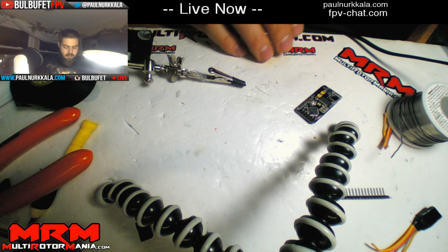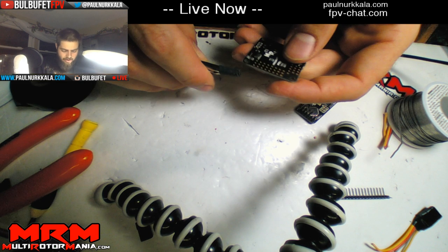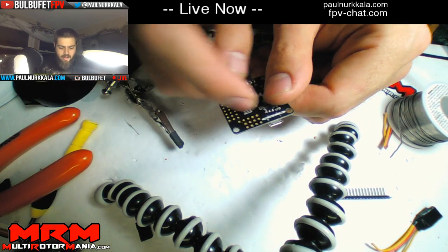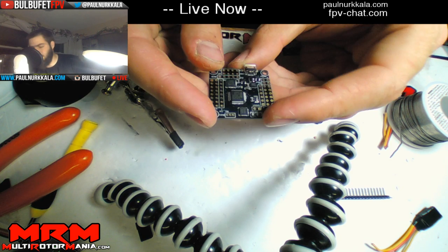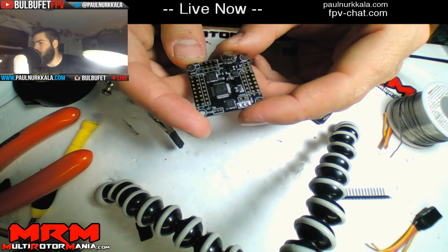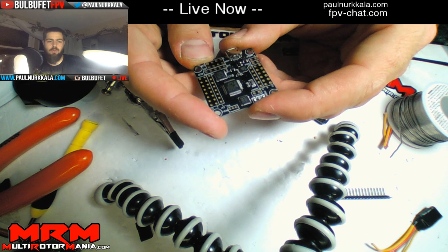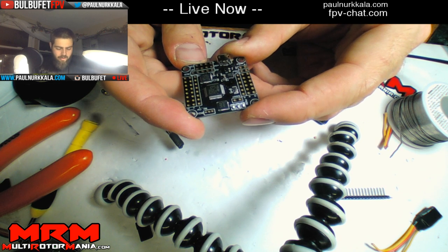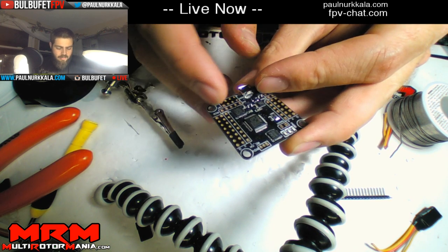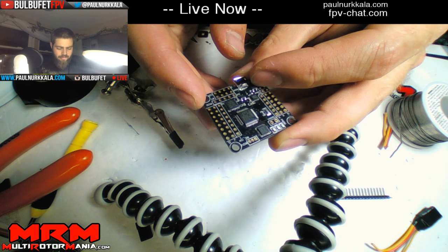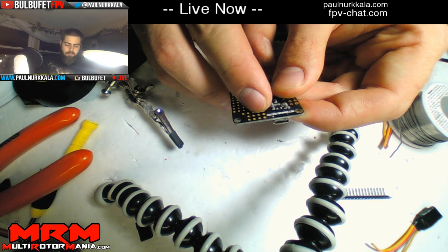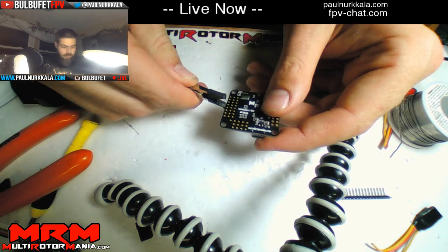Okay, so I'm going to pull this off, and I'm actually going to do it upside down so that the wires are all hidden out the bottom. I like it when my flight controller has zero to a few pin headers or wires coming out of the top. So we've got ground on this side and the other, RX on the far. So this should be ground, positive, RX, TX. So we've got to tin this up too.